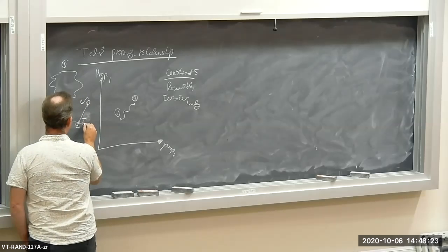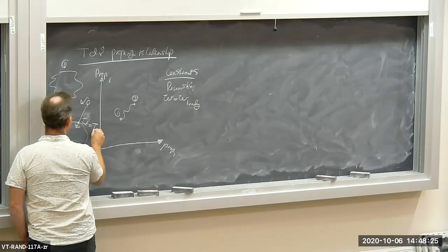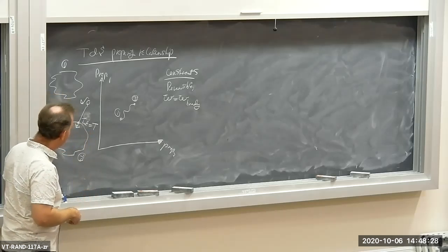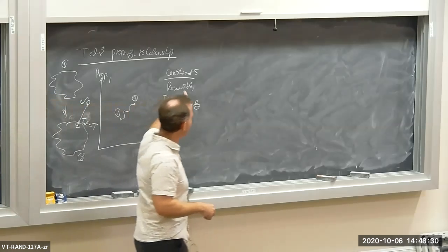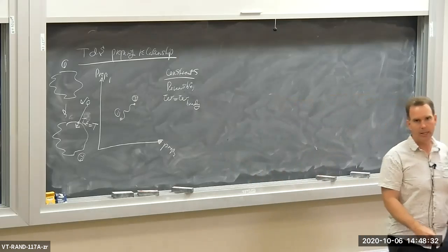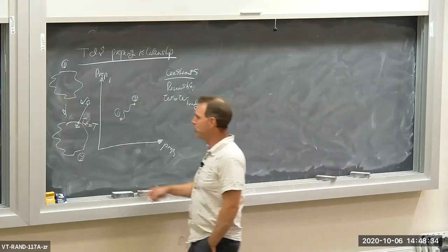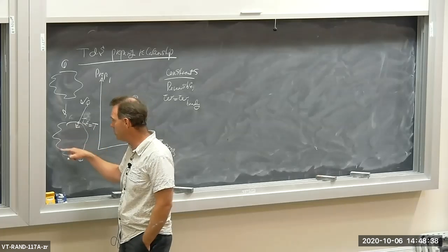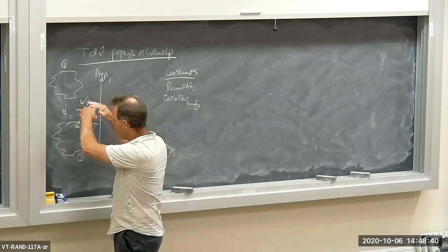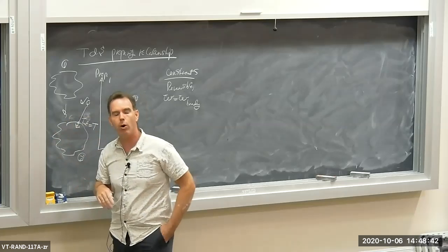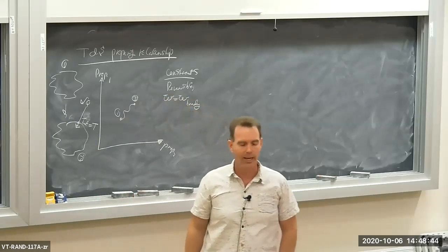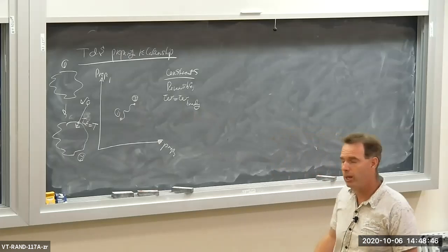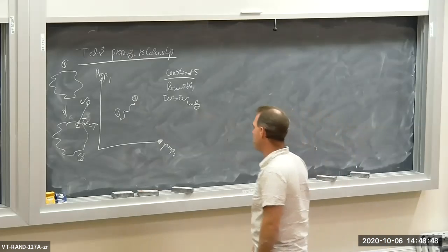So the T interaction is equal to the temperature of the system. Now, that actually falls from the reversible process. If the temperature here at the surface of my system was not the temperature of the system itself, then as the heat flowed into the system, it would flow across a temperature difference. And heat transfer across a temperature difference is irreversible.